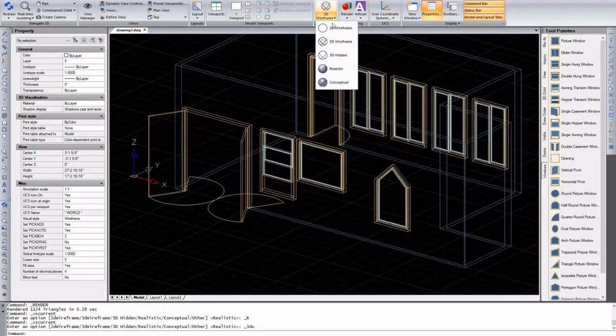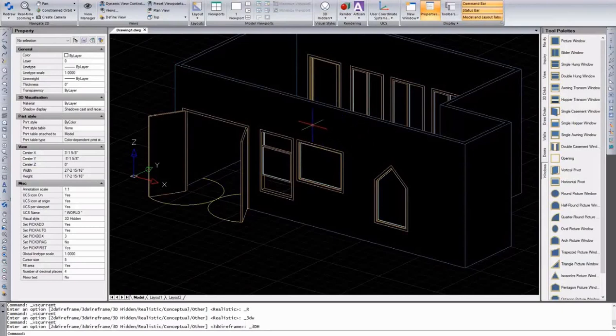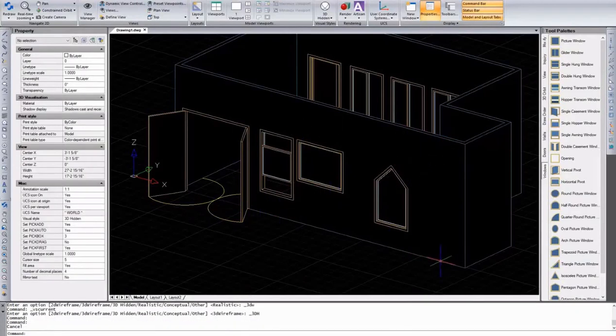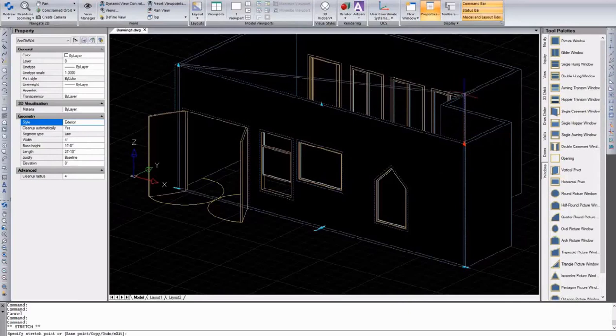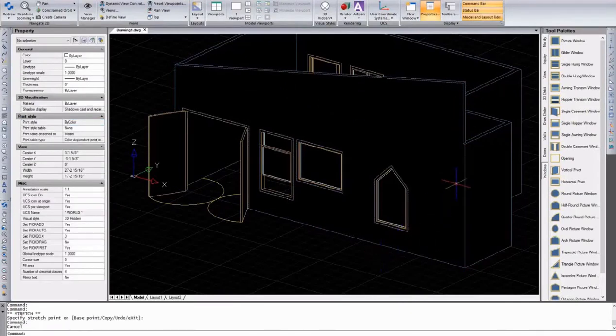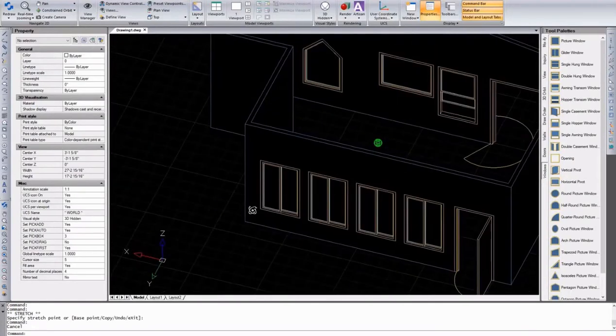It's working pretty well. So these are our standard architectural desktop doors and windows objects and styles. So if you bring this over into AutoCAD Architecture, it's going to recognize these. You'll be able to support grip editing, be able to add new openings into these walls, and be able to modify these styles as well. Of course, there's grips and things on the walls as well, and the walls have properties, so you can come in and make some changes to walls too. Define the cleanup radius. Of course, you have the style information that you can change, whether or not you want to change the width, the base height, and then you also have your grips that you can control some things with too. So you can do quite a bit with just the grips and the properties pane and the styles.